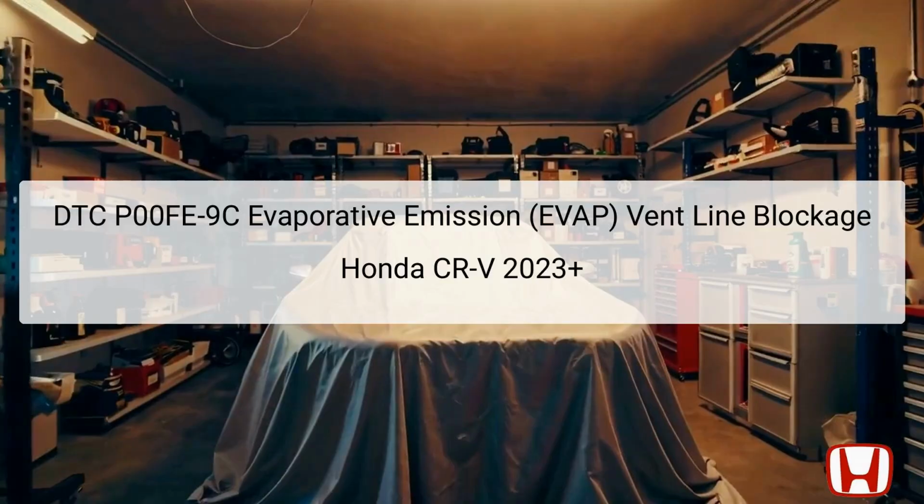The DTC P00FE-9C refers to an evaporative emission, EVAP, vent line blockage specifically for the Honda CR-V 2023 and newer models. When this code is triggered, it indicates that the Powertrain Control Module, PCM, has detected an issue with the airflow in the EVAP system, a critical component designed to trap fuel vapors from the fuel tank and prevent their release into the atmosphere.